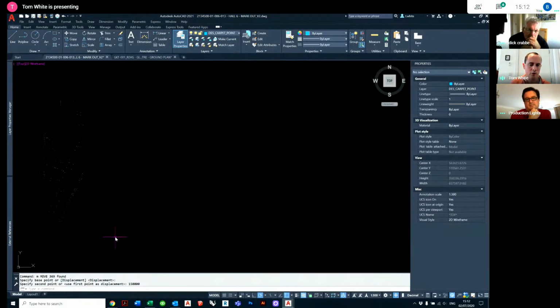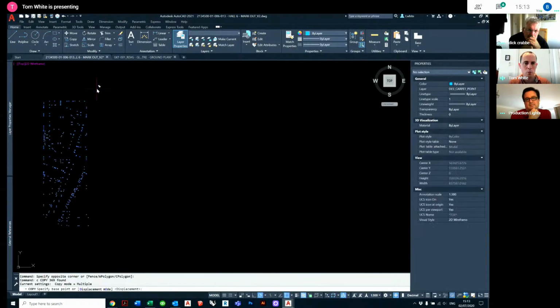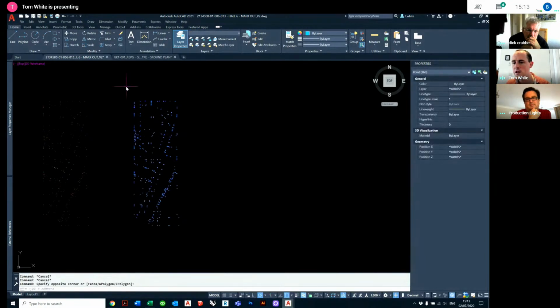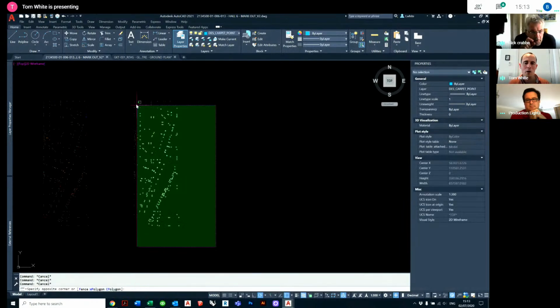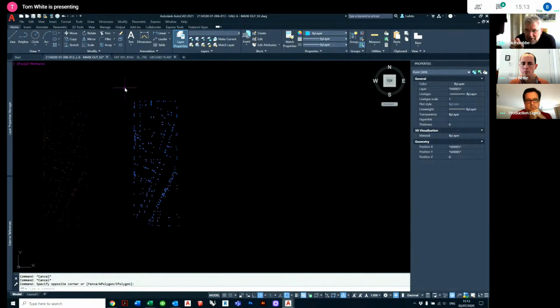I believe that I can think of two ways to do this. So I'm going to copy this another 150 meters. I could select all of these 369 points, and we can see that there's a X varies, a Y varies, and unfortunately there's a Z varies. So when it has the word asterisk varies asterisk, it means there's more than one item which the information within it doesn't match. So in this circumstance, because I know that I can override it, I could override Z varies to 0, enter. So, and that will move all of them down to a 0 Z-axis.